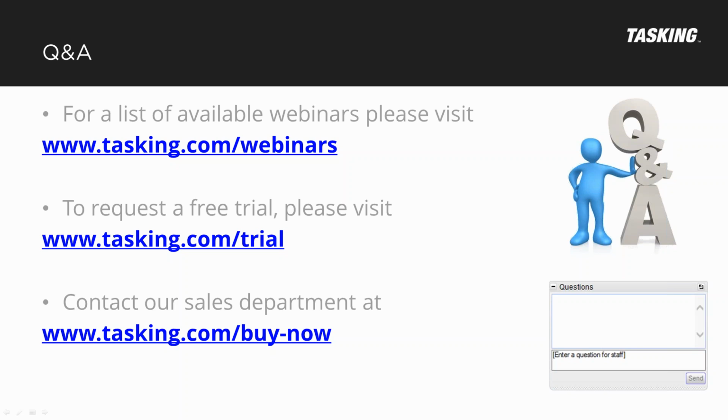Okay, there's a question. Are there guidelines for using different vendor compilers and the tasking compiler? No, there is no guideline. The reason is that you actually have some registers for transferring parameters and addresses, and these are not specified by the EABI, and each compiler vendor specifies their own way of how to use these addresses. So for example, you can't link together tasking and other compiler vendors because each vendor implements it differently.